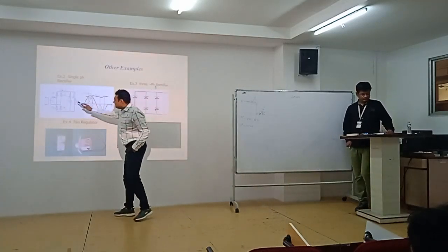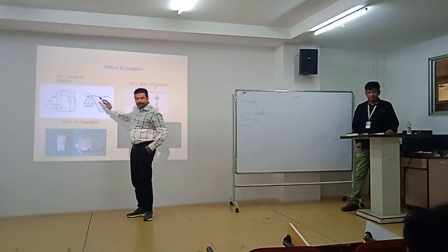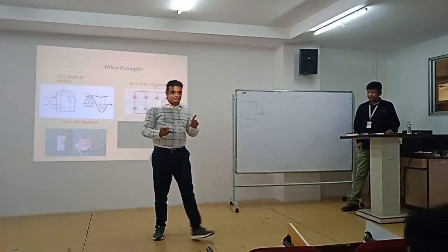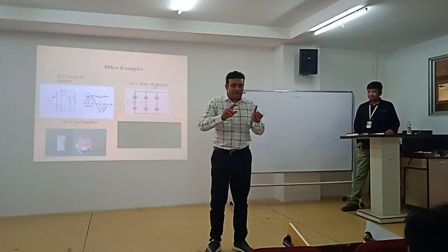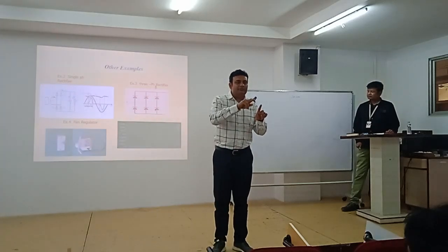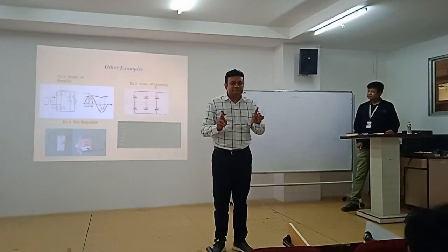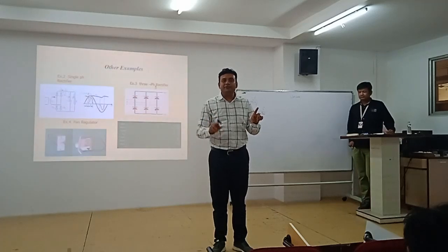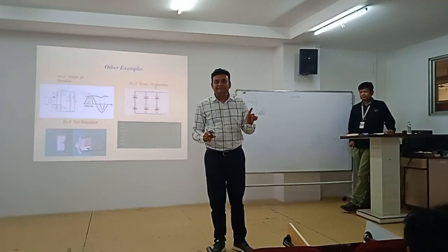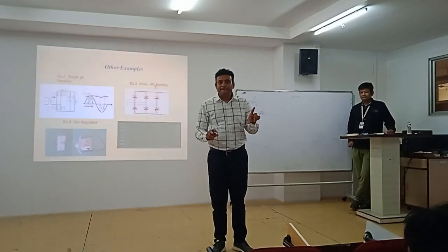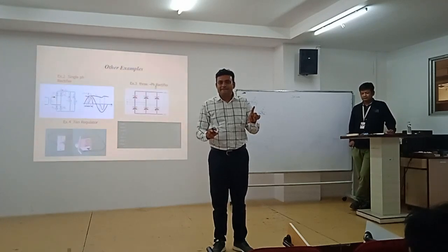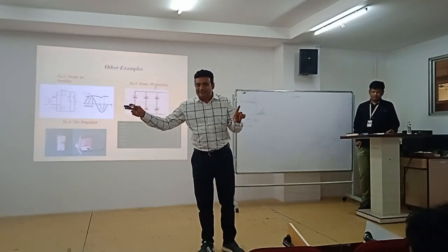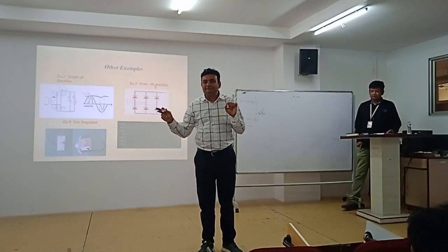For a single phase rectifier, if you see the pattern of source current, it will be a single pulse per cycle. And if you take three phase, it will be two pulses per cycle. The rectification is DC, but what happens to AC?